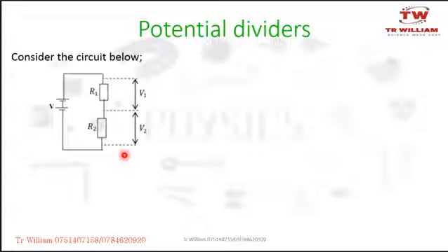It is changing. So if I'm to determine the current, how will I get it? First of all, before I determine the current, I need to know what is the resistance in the circuit. So since it is a series connection, the total resistance will be the resistor R1 plus R2. I think this is not new to you. You must have looked at it under voltage, resistance, and Ohm's law. Then from Ohm's law, voltage will be equal to current times resistance.